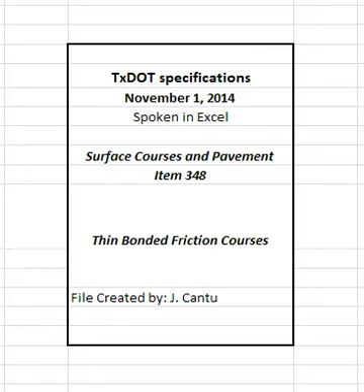Comply with all regulatory requirements stipulated for RAS by the TCEQ. RAS may be used separately or in conjunction with RAP. Process the RAS by ambient grinding or granulating such that 100% of the particles pass the 3/8 inch sieve when tested in accordance with Tex-200-F, Part I. Perform a sieve analysis on processed RAS material before extraction, or ignition, of the asphalt binder.